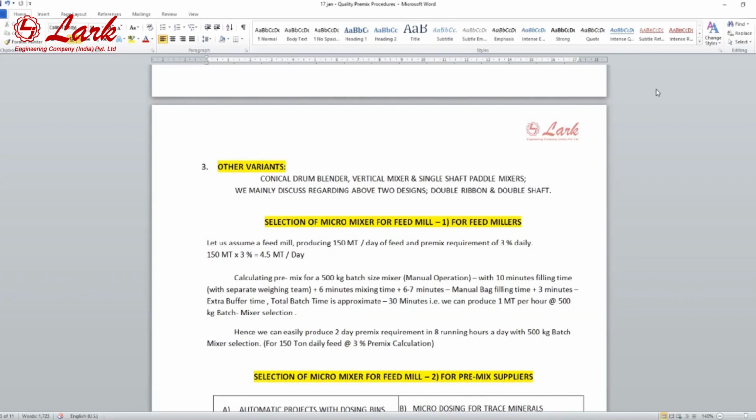Then a VFD at the crumbler feeder, and then a very important VFD at the blower, that reduces power consumption and helps to cool the feed with respect to the season and the moisture content. In the blower there is only damper setting for the cooling, but with the help of the VFD we can change the impeller RPM and get the desired suction with respect to the moisture content of the feed. So we have 4 to 5 machine applications of the VFD.